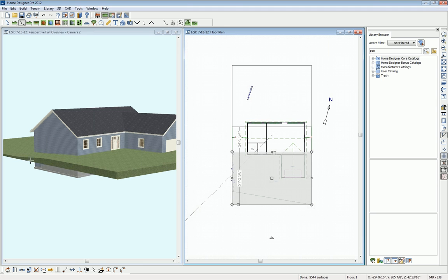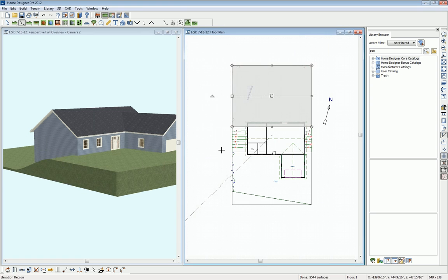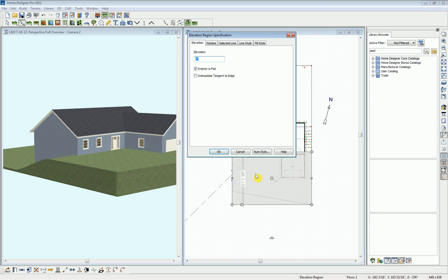And you'll see that it will also give that automatic slope option. So let's open this guy up and do -96 and see how that alters. All right, there we are. I do need to bring down that front pad a little bit here just so it doesn't interrupt with the rest of our house. We need that to be in our foundation a little bit there.